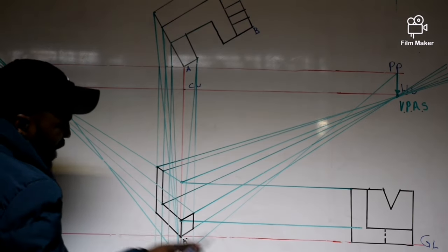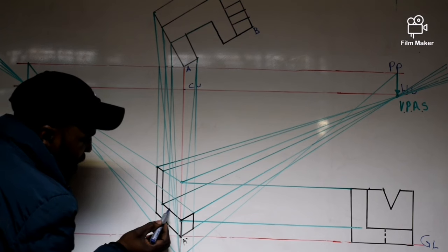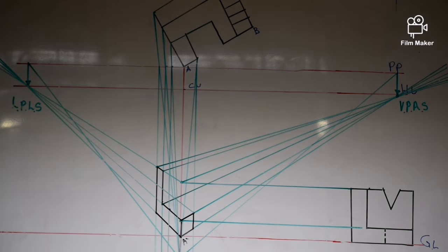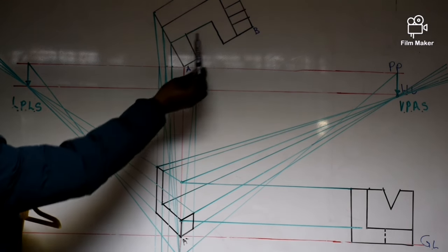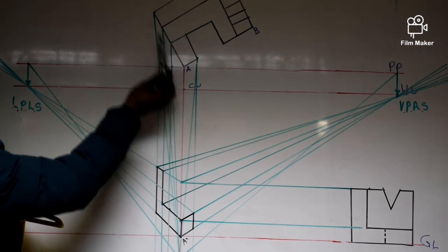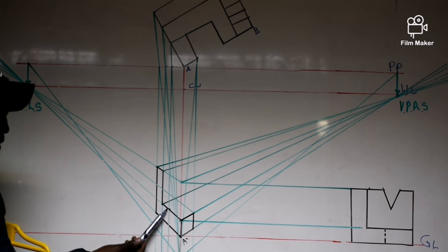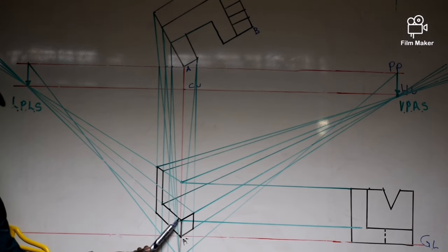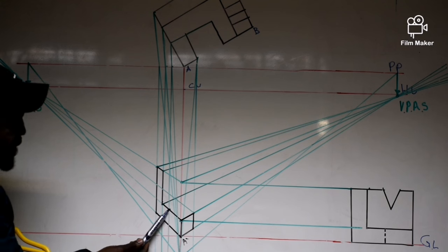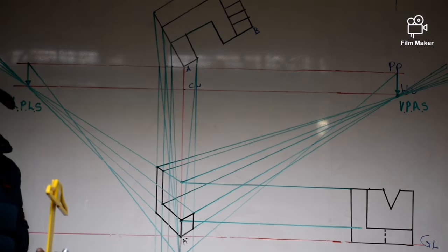So I want you to get this point. It should be somewhere there. Look, where is it? It's at the edge. Remember, you took it to the outer edge of your drawing, isn't it? So, same applies to here. You have to get it along this line. Do you have it? Once you get along that line, take it to a vanishing point of the right hand side.